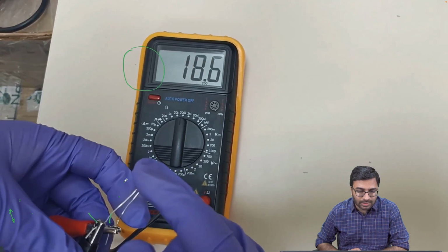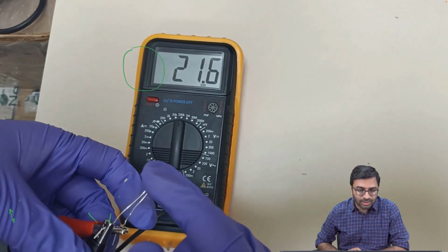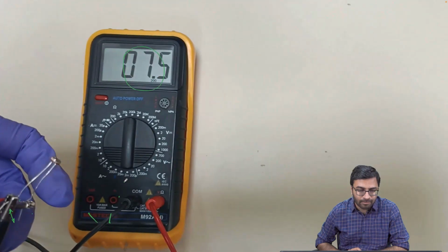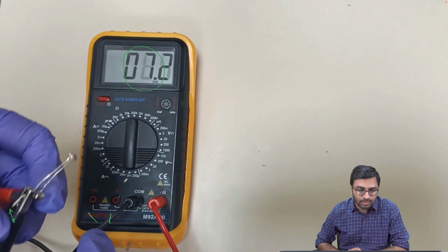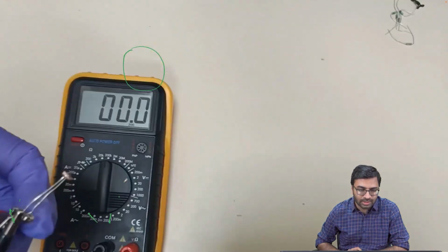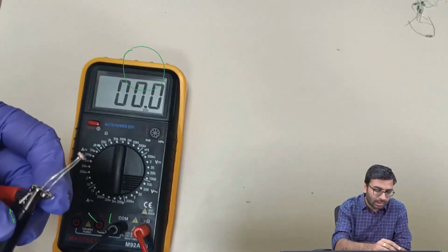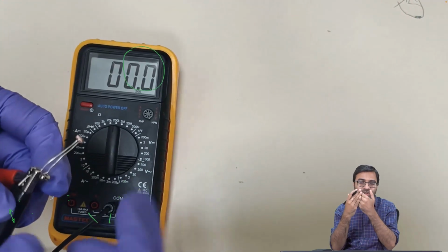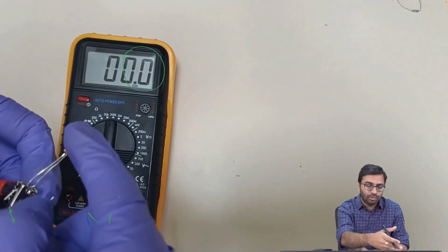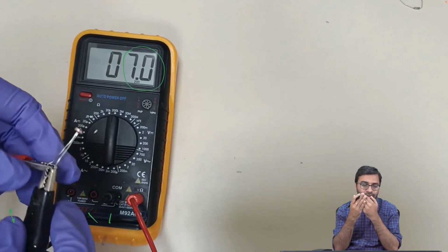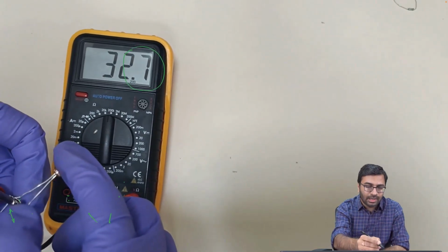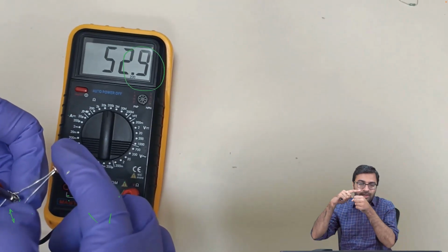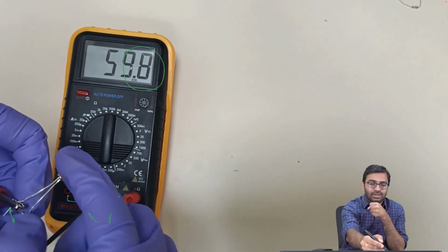Now in this case, see, when you touch it, the resistance increases. When you leave it, it's like 7 kilo ohm. See, now the resistance is 0 because these two terminals are touched with each other. Now if you touch it, the resistance will be 0. See, no response. You will see no response. So you have to make sure that these terminals are not shorted. The moment you take it out, again, the moment you put the finger on top of the sensor, it goes to around 60 kilo ohm.